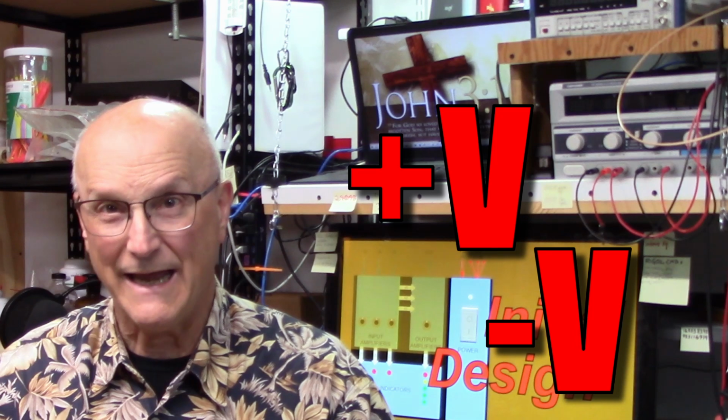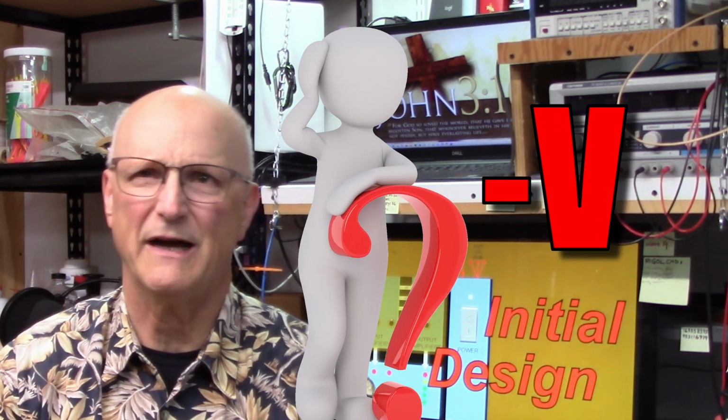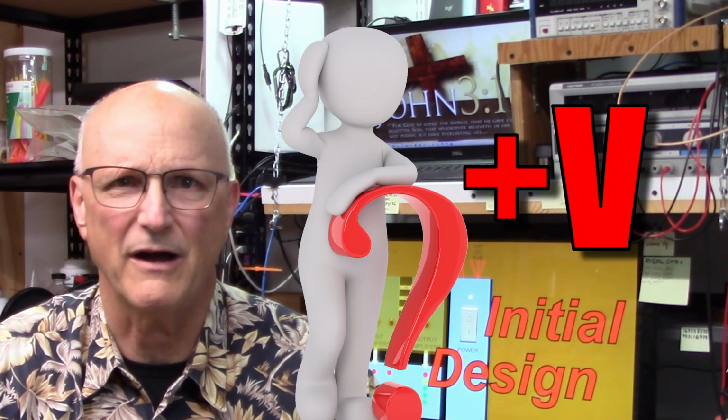Originally, I was going to have the entire design operate off of a single positive supply. But I've changed my tune on this because of the situation with the indicators function block. This means that we need both a positive and a negative power supply of equal voltage. But we're faced with a problem. We only have a positive input voltage. How on earth do we create a negative supply from a positive supply?